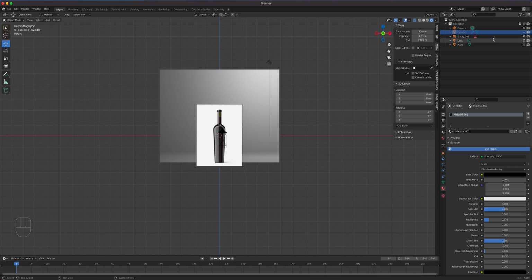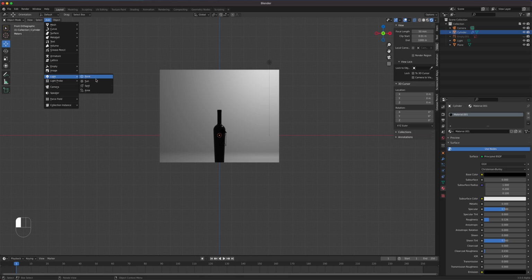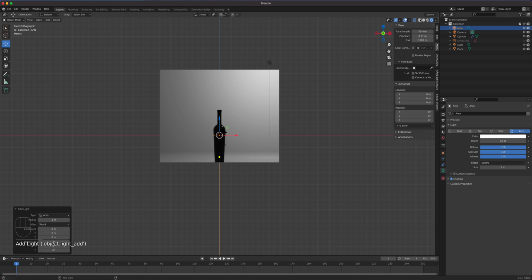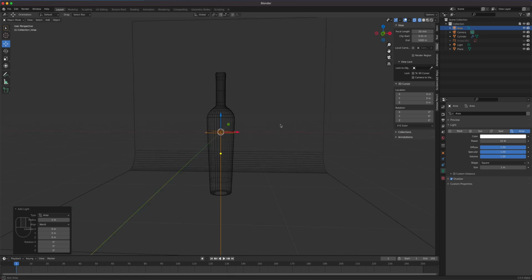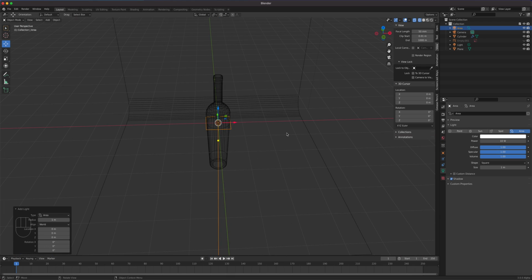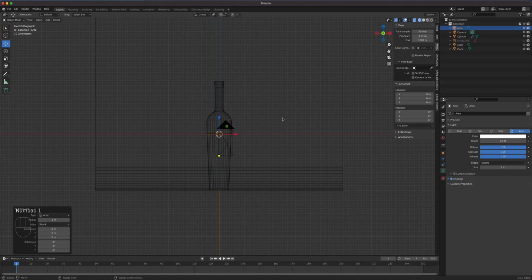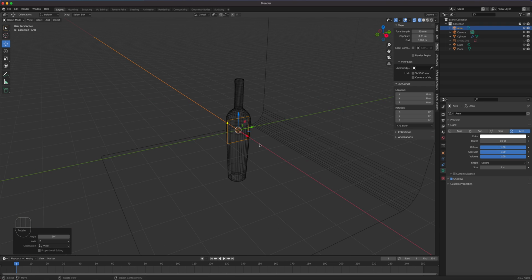Okay, so let's kind of copy that. Right, so let me hide the empty, which is the image. So I'm going to click Shift A, or you can go to add right here. It's the same thing. I'm going to go to light, and then area light's what we want. Okay, by default your area light is going to be pointing down, and it's this square shape. Okay, so let's position it the way we need it. So I'm going to go back to the front viewport here. I'm going to press rotate, which is R, but I'm going to hold down control so that when I rotate this, it snaps to 5-degree increments, so I can eyeball it and make a 45-degree rotation, so it's aiming this way, that's the aim right there.